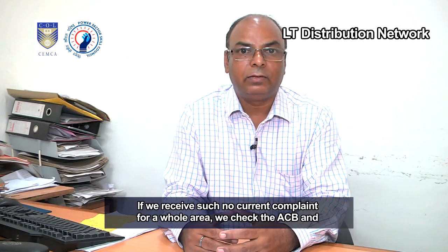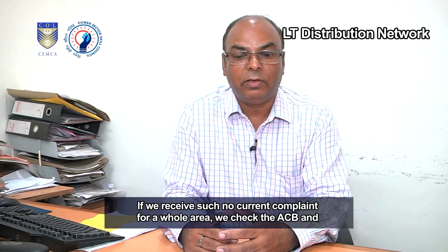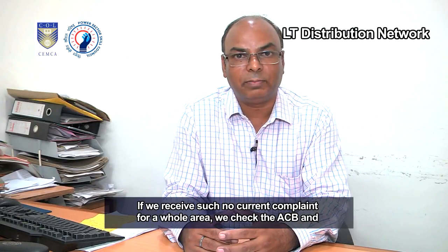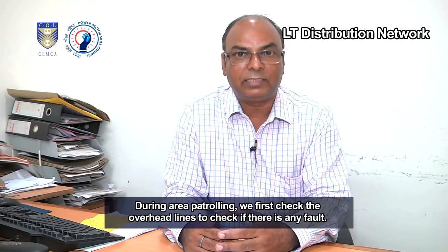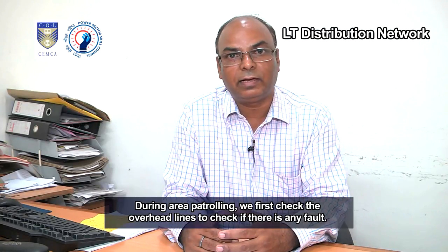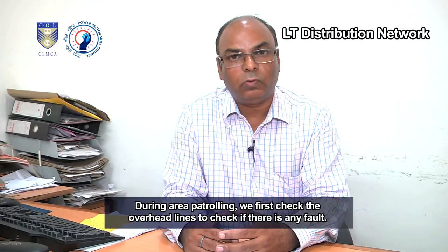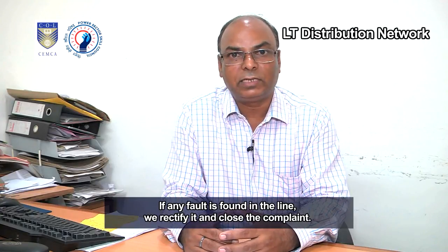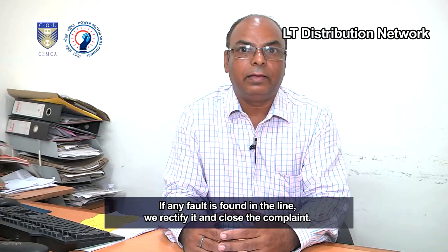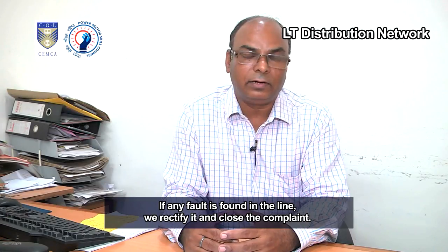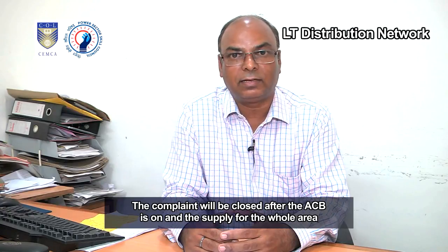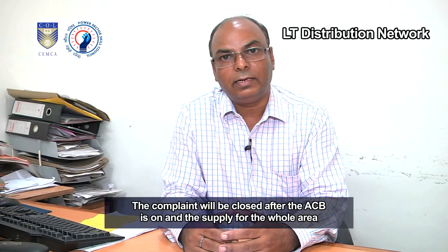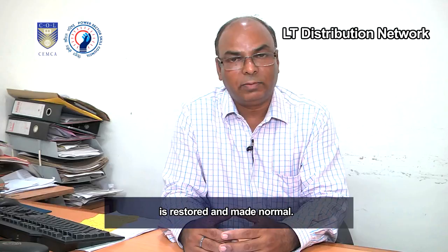If we receive such a no-current complaint for a whole area, we check the ACB and then do area patrolling. During area patrolling, we first check the overhead lines to check if there is any fault. If any fault is found in the line, we rectify it and close the complaint. The complaint will be closed after the ACB is on and the supply for the whole area is restored and made normal.